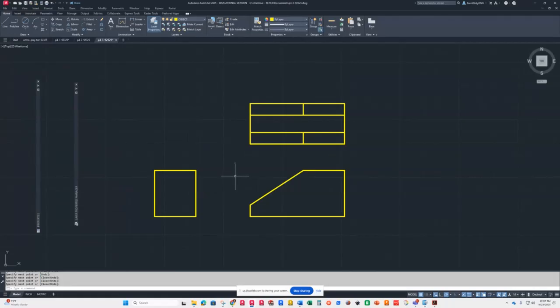Now, in the book, what they would have done instead of drawing this, they would have drawn their miter line off of this corner. Well, I don't have a corner to go off of, so I'm just going to do my method, which is I drew the outline of this view, and I just make this connection here where they line up, and then I can go at 45, which is 135, that way. And see, if I were to draw a line from here over, it would line up. See, this is the front of the top view. This is the front of the side view.